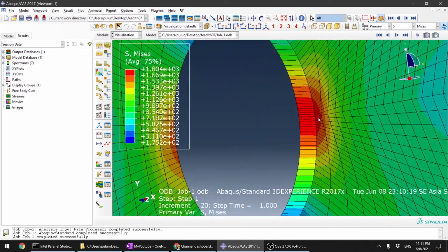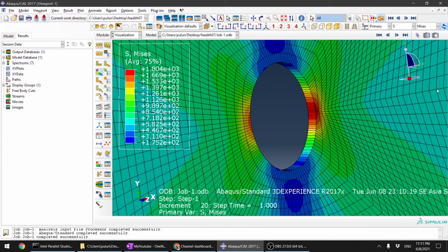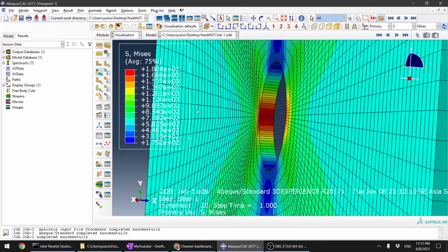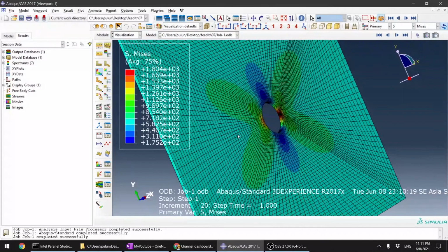And as you can see here, there's no strange deformation here. The previously strange deformation is due to the fact that we assigned this bias here, but we didn't assign the bias at this one, so they don't have the same setting, right? So it's really nice right now.